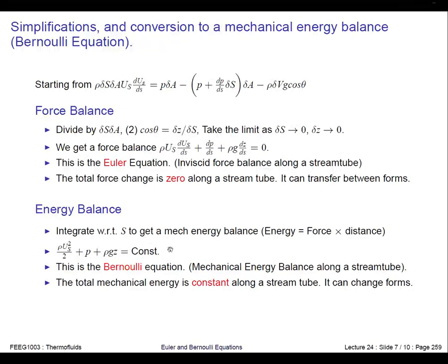And this pressure at no velocity is called the stagnation pressure, and it's quite important because effectively it tells you how much stored energy you've got in your fluid. So if you think about a pressurized tank that's connected to a pipe, the amount of flow or kinetic energy that you can transfer to your pipe is a function of the pressure you've got in your tank.